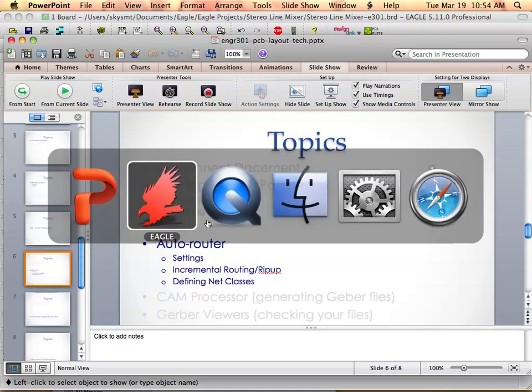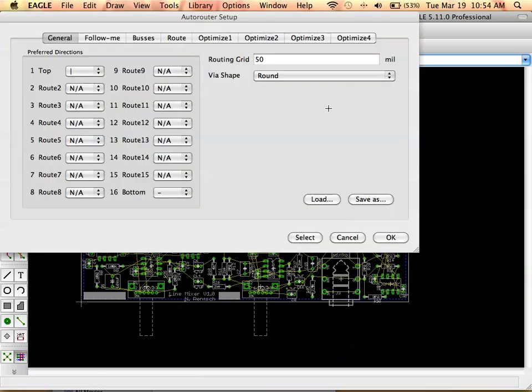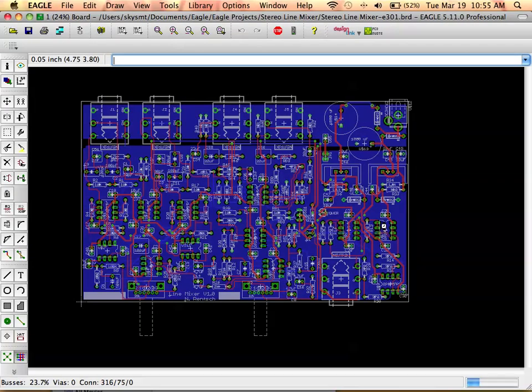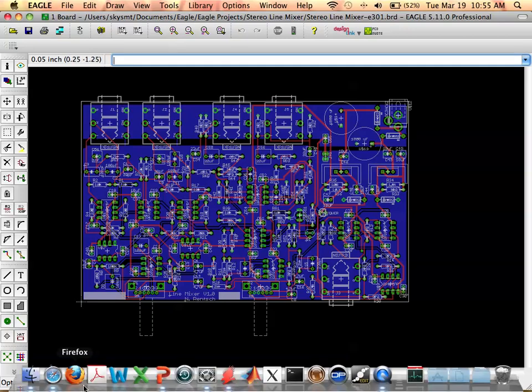If we want to now look at the AutoRouter, okay. So you've used this in part 0 of the project, designing a power supply, and what you did mostly was just type in auto and hit OK and just let her rip. With this board, with the way that I have things placed, remember I've done some very careful placing of everything, it's able to route this board with strictly the AutoRouter, just typing in auto once, with 100%.